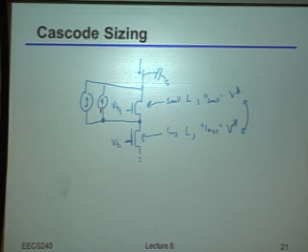Whereas if I tried to look at the current divider right here, it'd be really hard because I maybe know this impedance, but I don't know the source voltage. And this GM is only pointing one way and is only dependent upon Vs. Whereas if I look down in this node, I know what Vs is because that's directly a function of the current I'm injecting in the first place. So it's just easier to calculate that current divider by looking at KCL at that node.